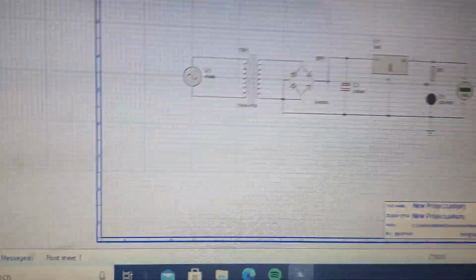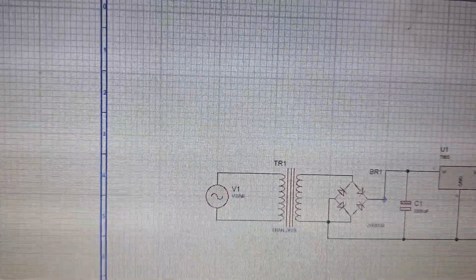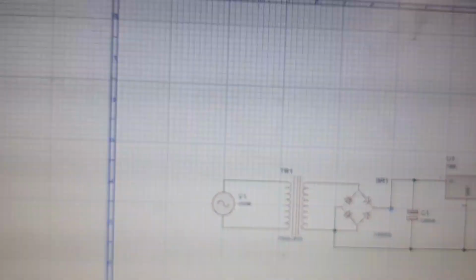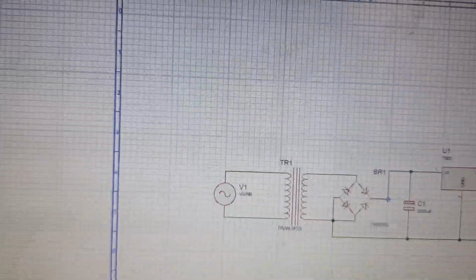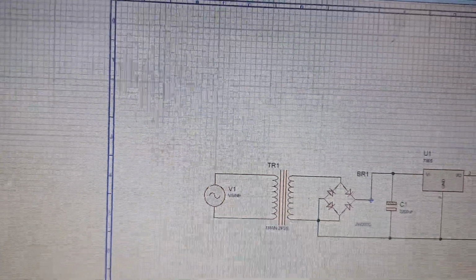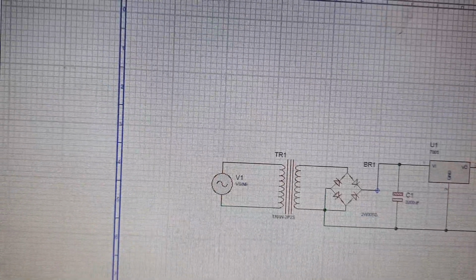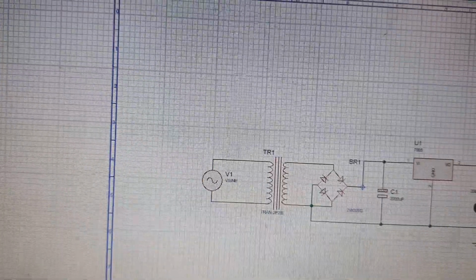Now moving towards the designing of the hardware. In hardware implementation, first of all apply the source voltage to the input pin of the 7805 IC. Capacitors are also connected in parallel with the source voltage and their ratings are 100 uF and 100 pF respectively. On the other side of the IC, we also connect two capacitors in parallel to the gained output voltage.